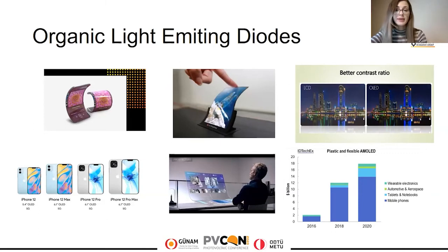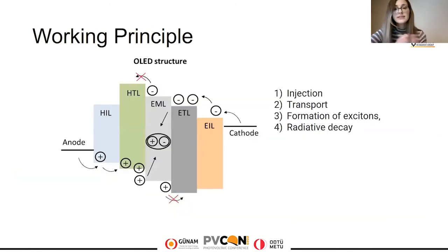To appreciate what makes this TADF process unique, one must first understand how OLEDs produce light. When electricity is applied to an OLED, positive and negative charges are injected into the device. Before light is emitted, a positive charge and a negative charge meet on the same molecule, forming an energetic state called an exciton. The electrically created excitons come in two varieties, singlets and triplets, with 25% of excitons naturally being created as singlets and 75% as triplets.